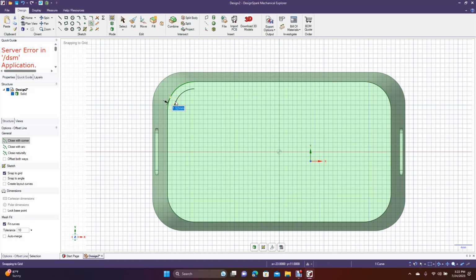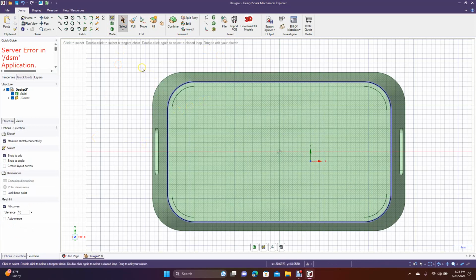We're going to make these little extra kind of legs for this thing to sit on. So we'll go ahead and go 1 millimeter, and we'll offset this one as well, and then do these over here. Click there and go to offset. Select 1. Okay, so we're going to have 4 of them.